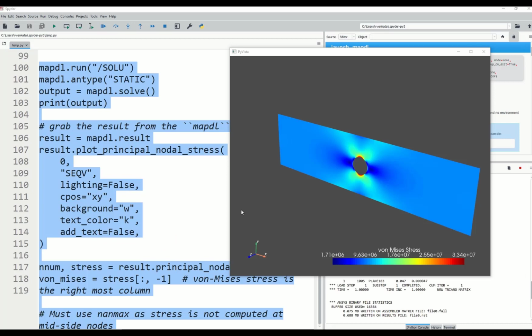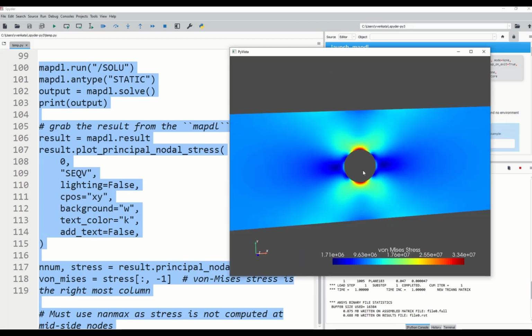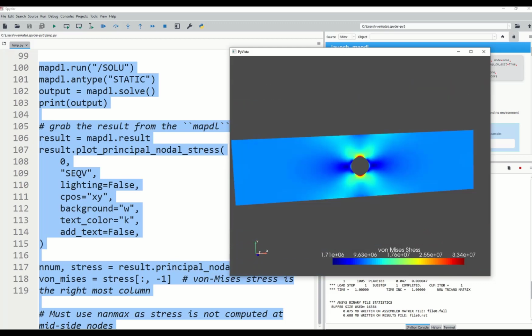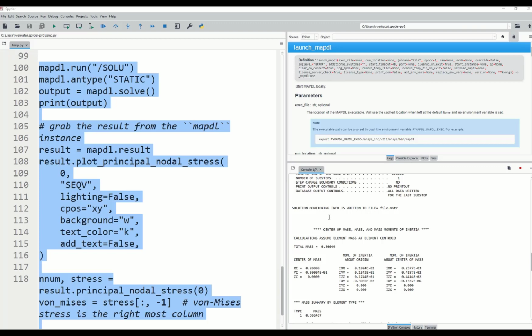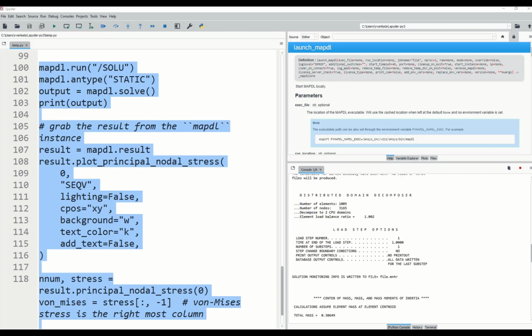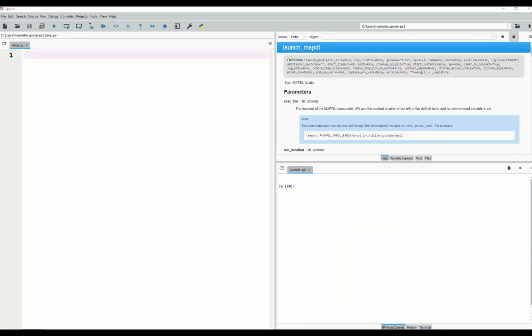You can even solve them and extract results using Python libraries like NumPy and plot the contours using open source libraries like PyVista. You can look at the solver output while it is solving right within the Python environment. Hence, you can automate the simulation end-to-end using PyAnsys and amplify the power of ANSYS products using tons of open source Pythonic libraries like NumPy, SciPy, and so on.